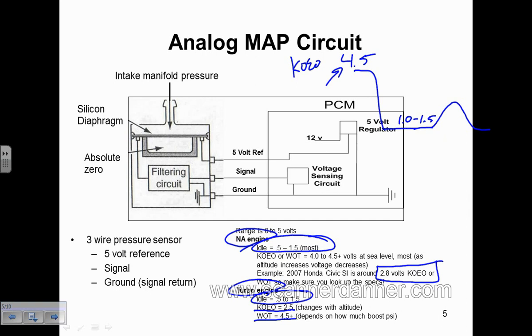Yes? That's why they don't get like a 2-bar, 3-bar MAP. Yes, a 2-bar or 3-bar MAP was your comment as far as upgrading. And the equivalent was 1 bar is, I believe, 15 PSI. So a 1-bar MAP would probably be this factory one, although I don't know if they would classify this as a 2-bar. It might actually be a 2-bar from the factory because at atmospheric pressure it's already able to read. So a 1-bar would be your regular MAP, but look how it's calibrated. At 1 bar, you're going to read 2.8 volts. And this has the ability to read higher.